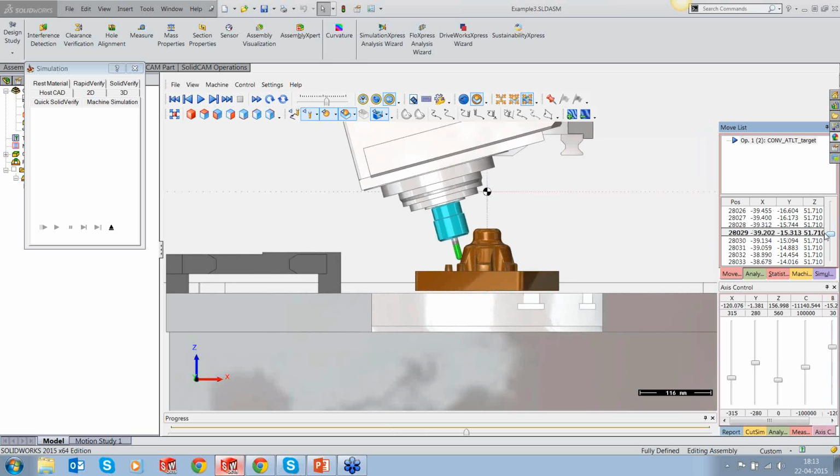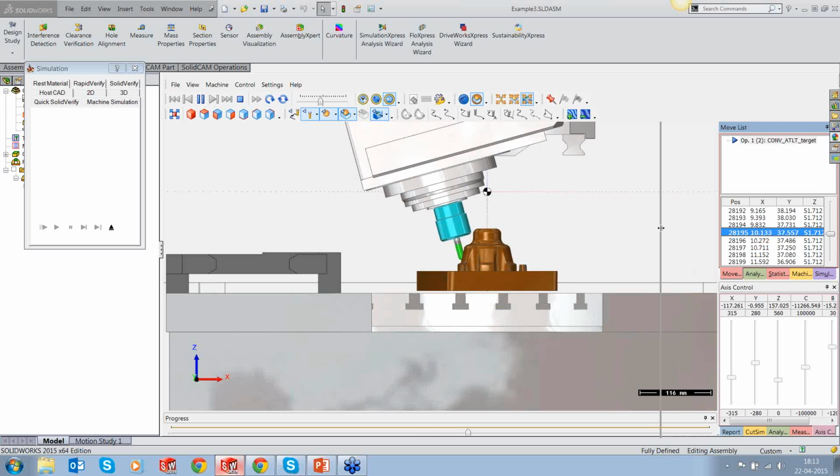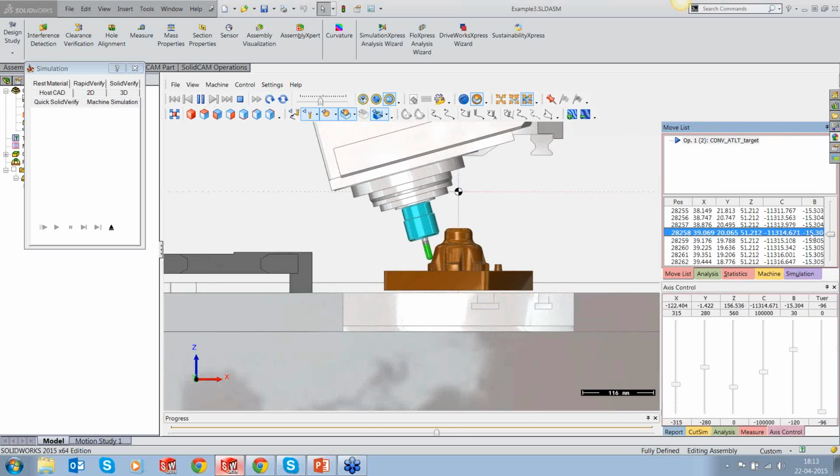Now what it is doing here is it's kept the head stationary and only the C-axis along with the X and Y are moving in order for it to compensate and create that movement. So it's pretty nice motions where your B-axis is tilted. It's tilted almost at minus 15 degrees. You can see on the side when I move the slider.